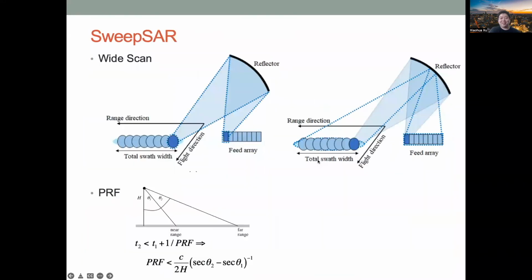All right, finally, SweepSAR. I want to cover just a little bit about how it works as NISAR is approaching, and it'll be in this new acquisition mode. Katya could probably add more to this part. So traditionally, the acquisition mode will transmit radar signals from the antenna directly. So the shape of the antenna sort of determines the footprint on the ground. That's why almost all the SAR satellites had swaths or subswaths with widths around 70 kilometers.